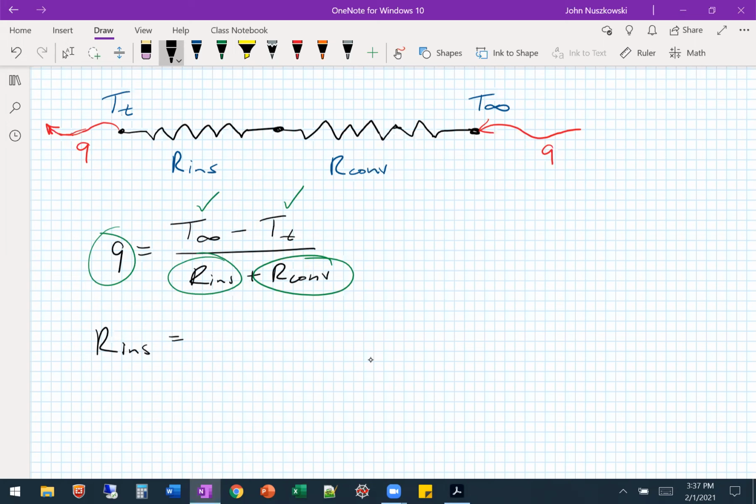Yeah, so it's going to be 1 over R1 minus 1 over R outer, so that R stays positive. R outer is a larger number, so that makes that term smaller. If R outer is larger, that makes that smaller. So you want the resistance of the insulation to be a positive value, if you're going by arrows and directions that way. Got it. Thanks.